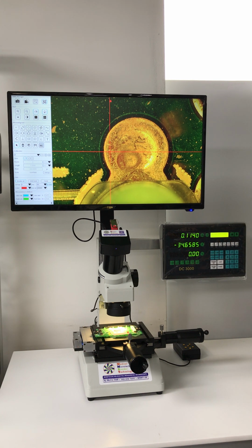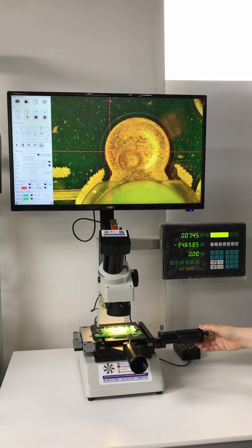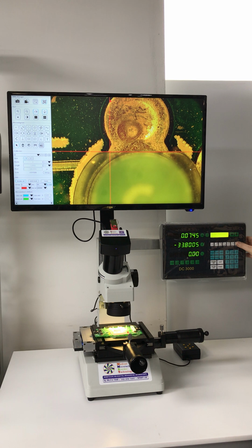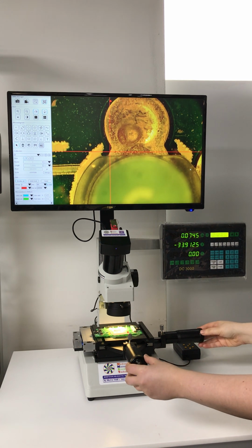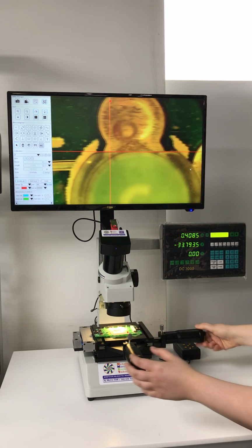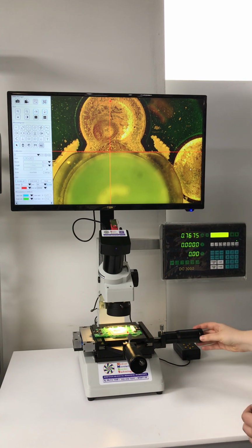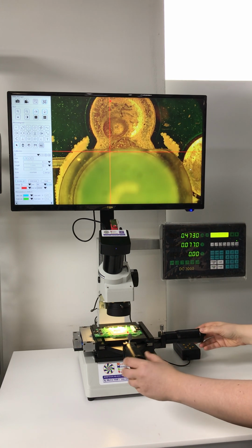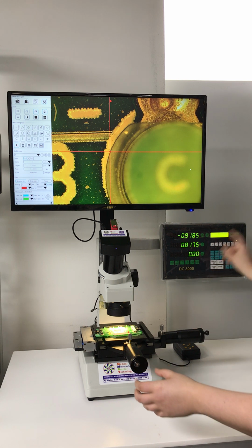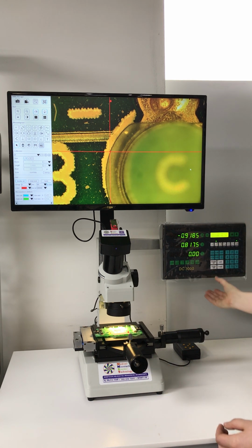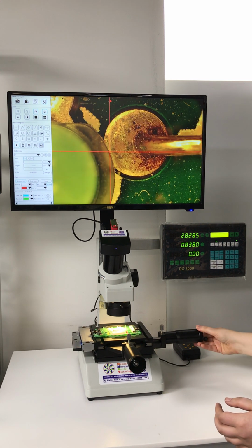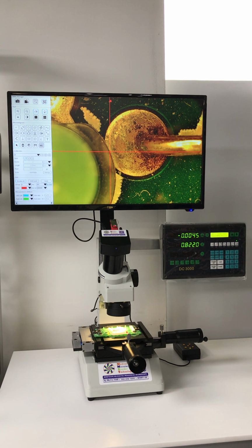to the main screen. If you also have a part that's skewed, what you can do is press the skew button. So we'll line up our part, and it's always best to do the horizontal one. Press 2 more. Now it's skewed. Now I can measure my part. Press enter. Oh, sorry. And what you'll do is you'll press your measurement, press enter, and we'll do 1 more point, and it'll give us our measurement.